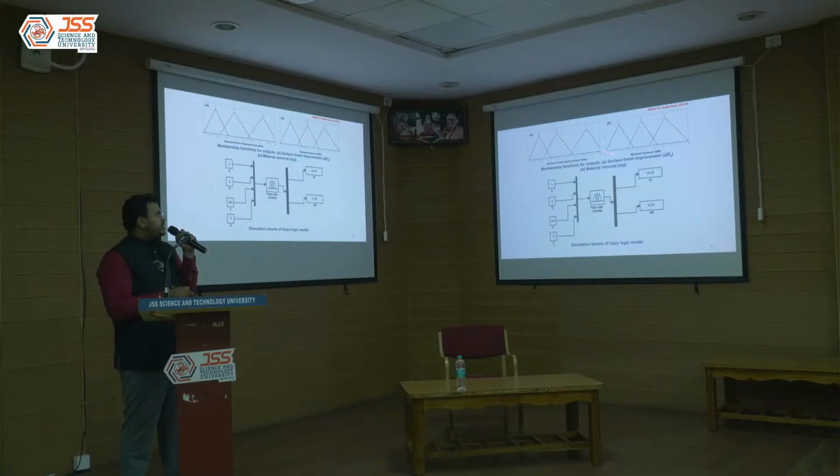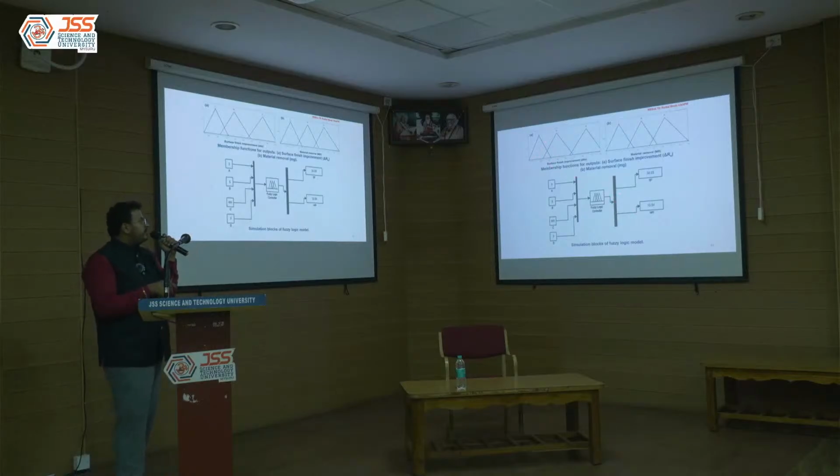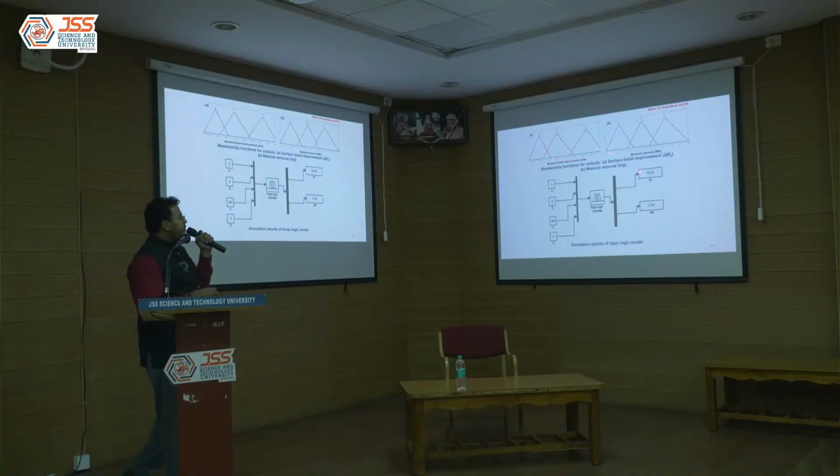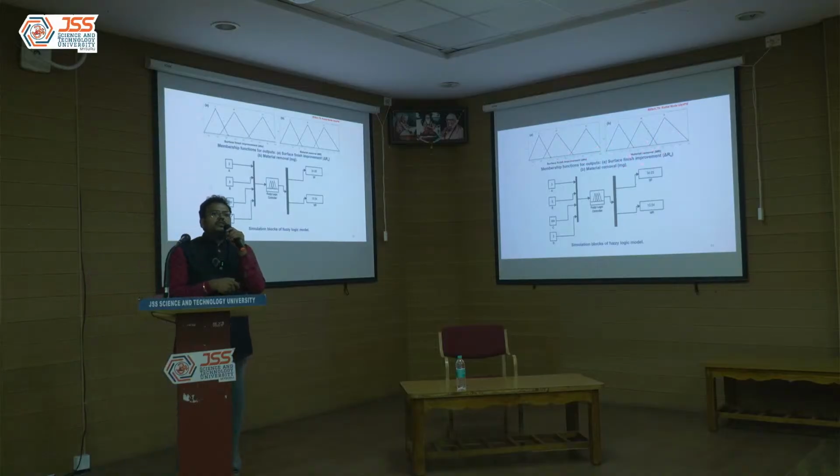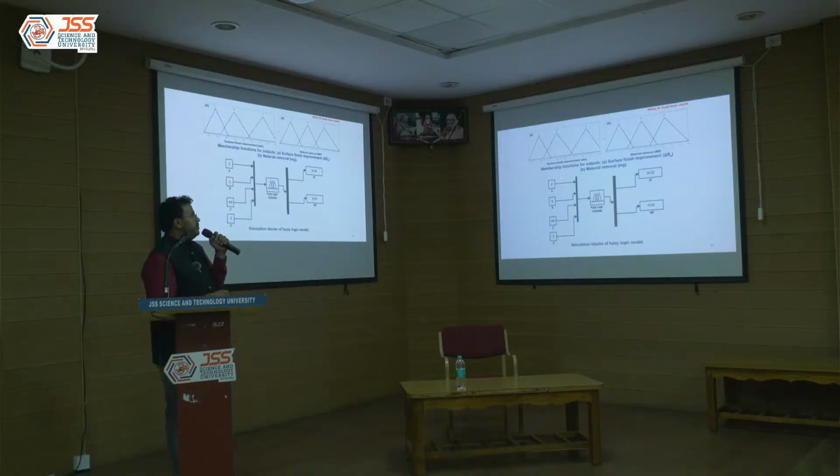Similarly, the simulation blocks of the fuzzy logic model are constructed using MATLAB, and we also created membership functions for the output responses. My output responses are surface finish improvement and material removal. I have given the ranges for low, medium, and high for the surface finish improvement as well as material removal. These ranges I got from the real time data, based on the 31 experiments I have conducted.